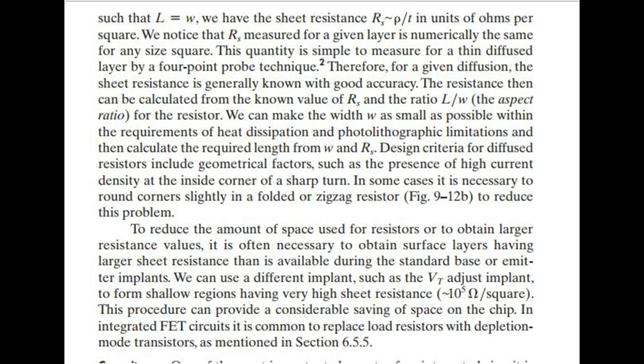Design criteria for diffused resistors include geometrical factors, such as the presence of high current density at the inside corner of a sharp turn. In some cases it is necessary to round corners slightly in a folded or zigzag resistor, Fig 9.12b, to reduce this problem.